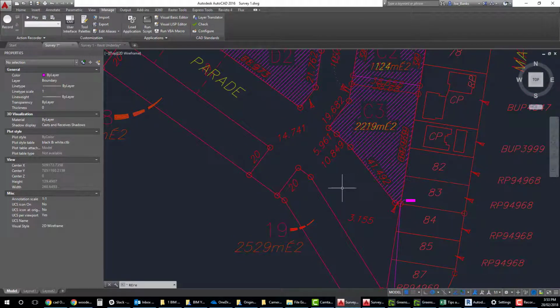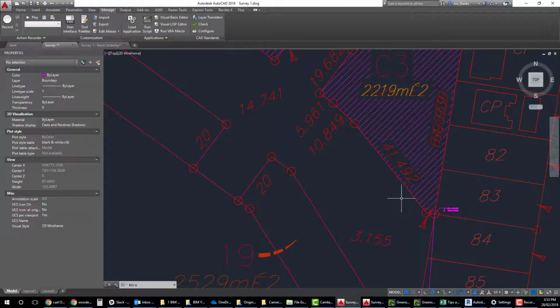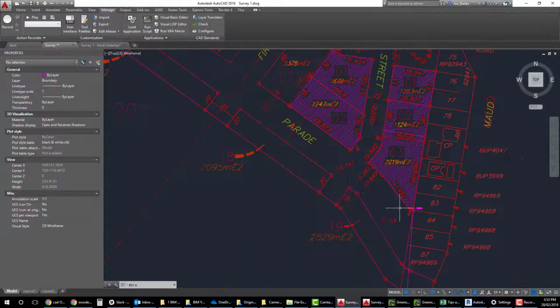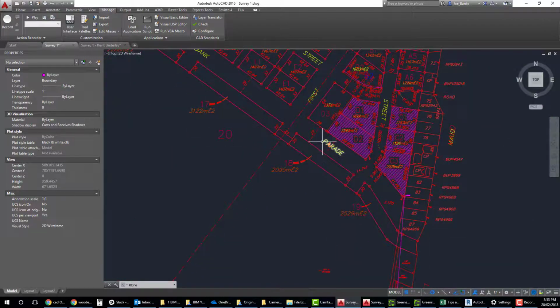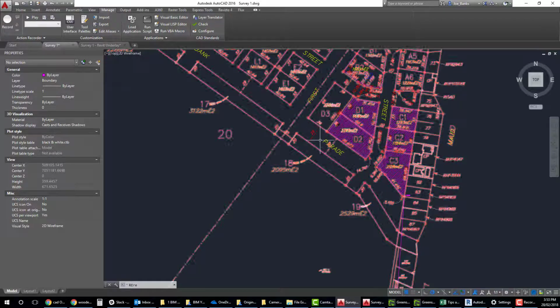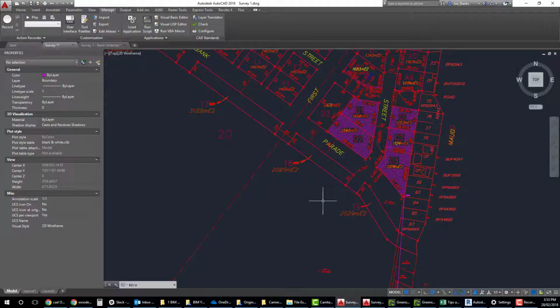If you've got a more detailed survey that has a surveyor's point marked clearly, something that's easily reproducible on site, the ideal location would be about here somewhere, where everything on the site is a positive number in the east and the north from that point. That's not super critical because generally we're going to measure everything to the survey point origin anyway.